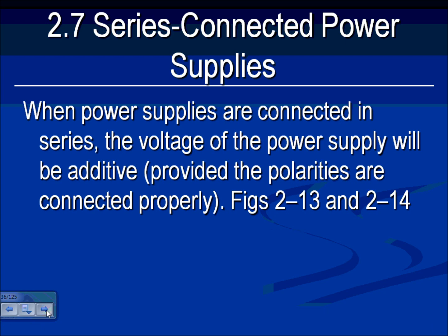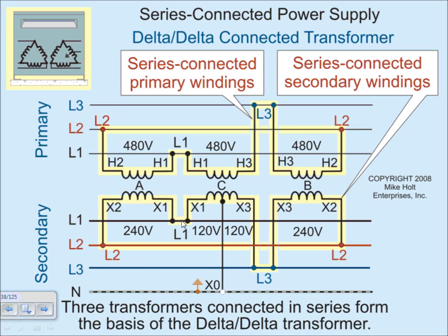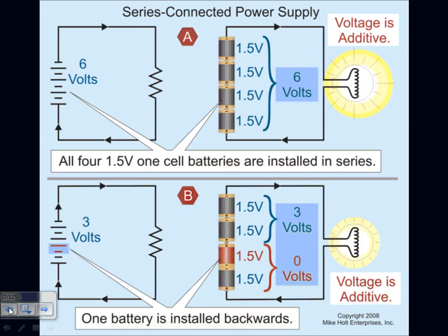Power circuit. When you're talking about the loss from the power supply, is that transformer efficiency? Or yes, efficiency of the generator, thank you, and the transformer. The generators and transformers, guys, mainly generators, because that's where the power started. Transformers are just moving the voltage from one level to another. They have impedance, and they have losses. They have mechanical and electrical losses.